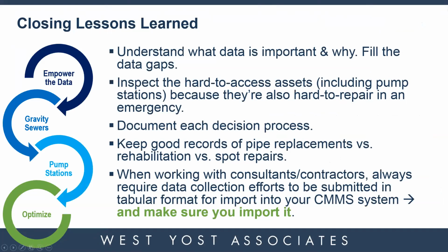So I just wanted to close with a couple of lessons learned after this four-year program from beginning to end. I think it's important to understand what data is important and why, and to fill those data gaps. If you don't have CCTV data for part of your system, start to collect it once you realize how important it is. Also, inspect the hard-to-access assets, including your pump stations, first, or as soon as possible, because they're also hard to repair in an emergency.